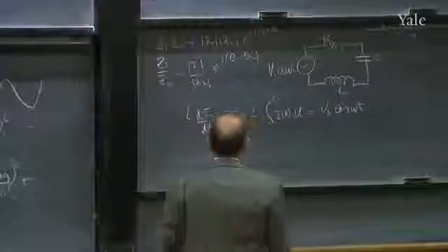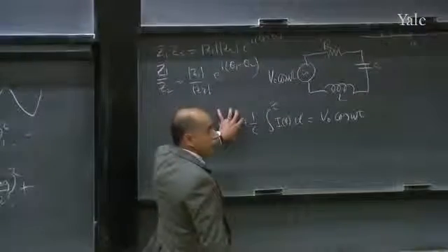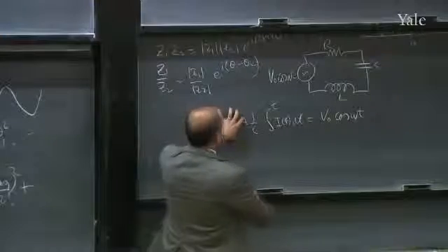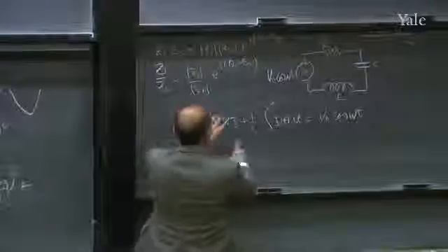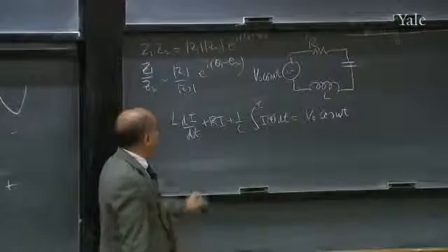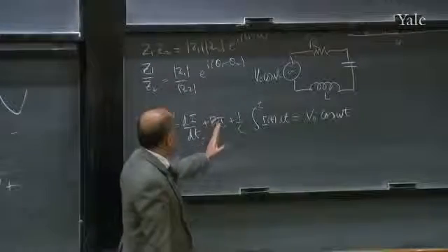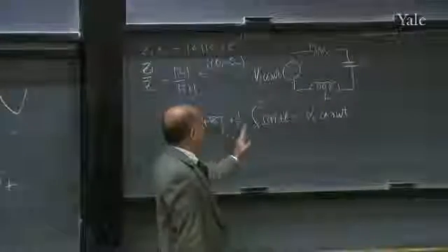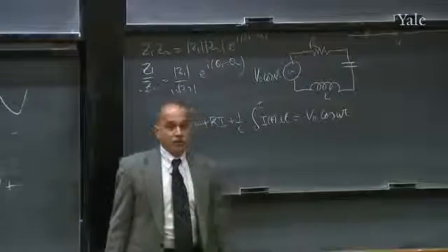You cannot do that, because sine will become a cosine and cosine will become a sine. In the LC circuit, when you didn't have this term, we were okay, because if you pick a sine, this became a cosine, and that also became a cosine, and you can combine them to get a cosine. But you cannot have di/dt, I, and integral of I all in one equation and all satisfied by a trigonometric function.